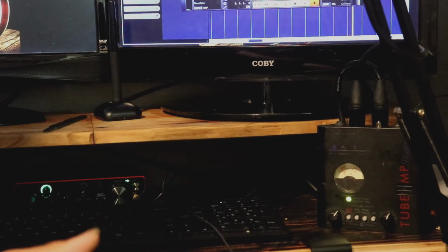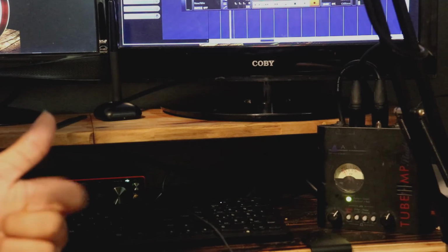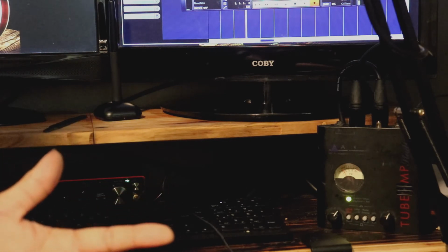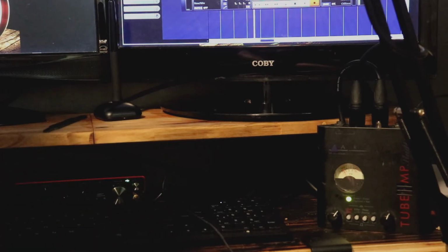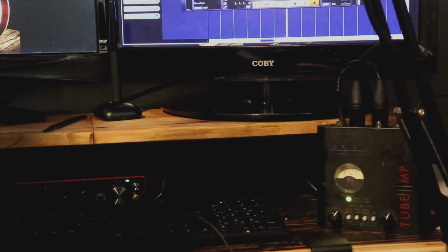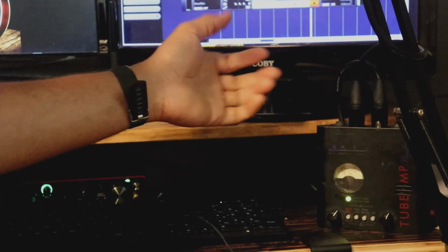Now keep in mind, I'm trying to make an active EQ, meaning that I'm either going to use op amps, transistors, or vacuum tubes. The easiest choice would be to use op amps. The second choice would be to use tubes, and I'll talk about why in a second.